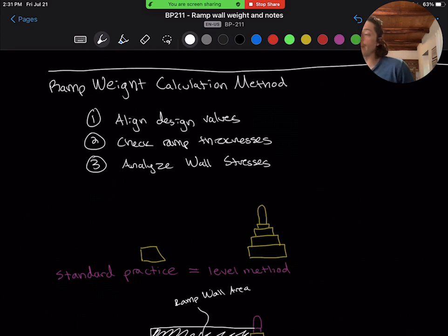And below, I've pasted two great examples of each method in the field, along with a sketch that shows the difference between the sloped and level methods of constructing ramp walls using a 3-tier abutment as an example. Remember that a 2-tier abutment would only use 30 and 50 centimeter walls, and a 1-tier abutment would only use 30 centimeter walls. So level walls are constructed by moving 1 meter down from the walkway hump and building 30 centimeter walls straight across.